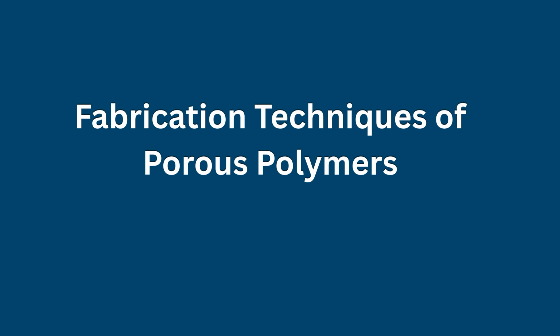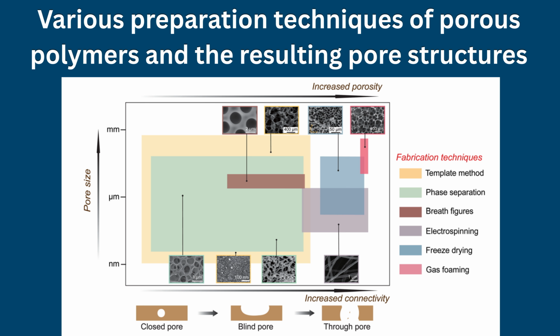Fabrication techniques of porous polymers. The fabrication of porous polymers relies on the inherent processability of polymeric materials, which can be dissolved, melted, or mechanically structured. A variety of techniques have been developed to control pore formation across multiple length scales, each offering distinct advantages and limitations. Electrospinning is a widely used technique for producing fibrous porous polymers with high surface area and interconnected pore